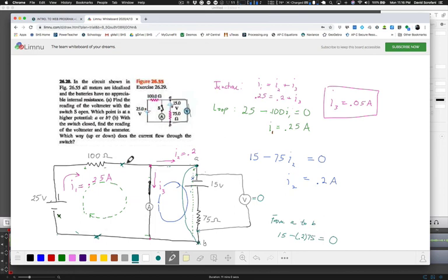It's also 0 if I go this from here to here, because that's a bare wire with no resistance. So regardless of what the current is anywhere, in the equation V equals IR, if you're using that equation to analyze things between this point and this point along this path, well, the R is 0, so the delta V is 0 between here and here.